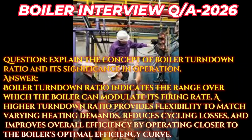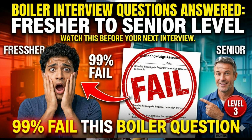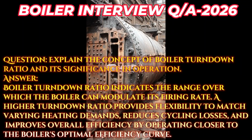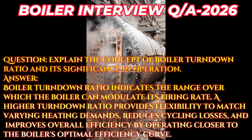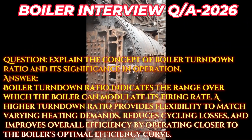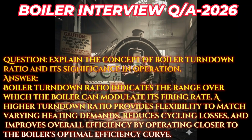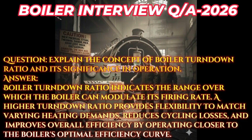Question. Explain the concept of boiler turndown ratio and its significance in operation. Answer. Boiler turndown ratio indicates the range over which the boiler can modulate its firing rate. A higher turndown ratio provides flexibility to match varying heating demands, reduces cycling losses, and improves overall efficiency by operating closer to the boiler's optimal efficiency curve.